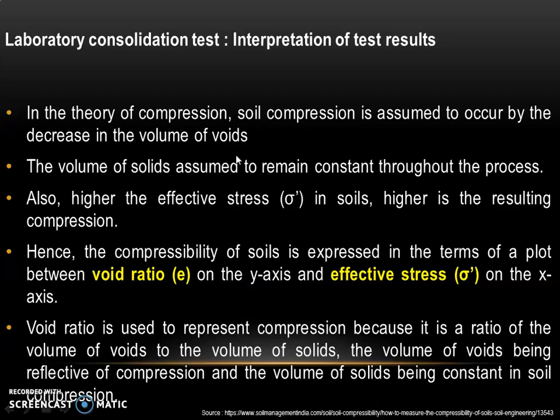Once the total load due to structure on the soil increases, there is increase in the total stress. In order to resist this total stress, effective stress, which is the stress exerted by soil particles, also increases. Hence, there will be higher compression.